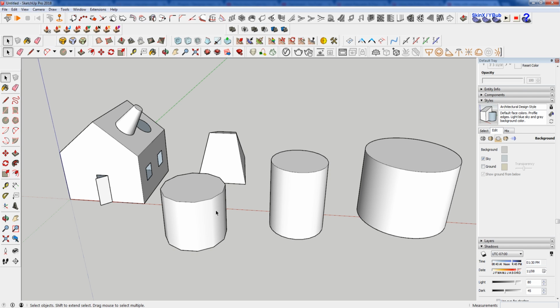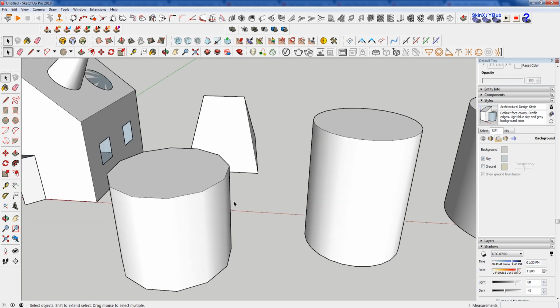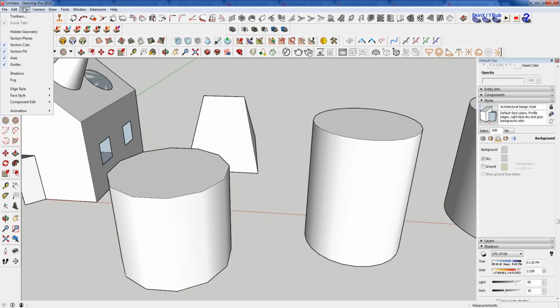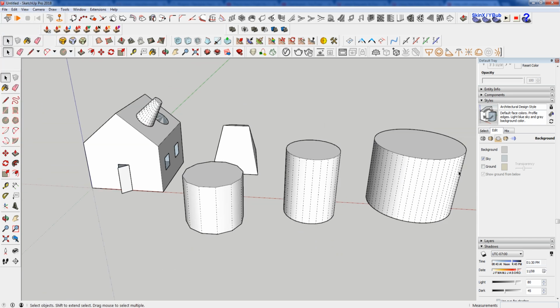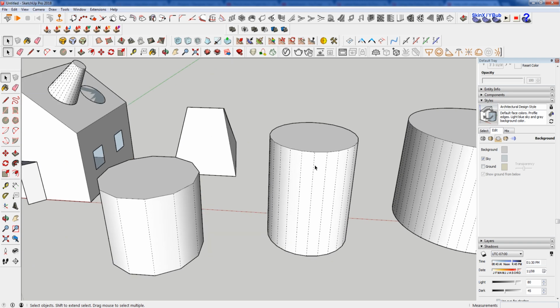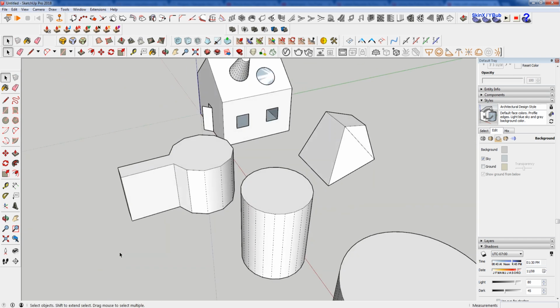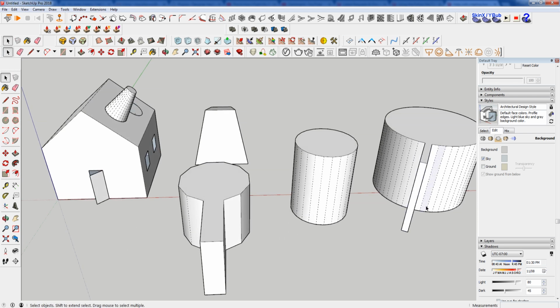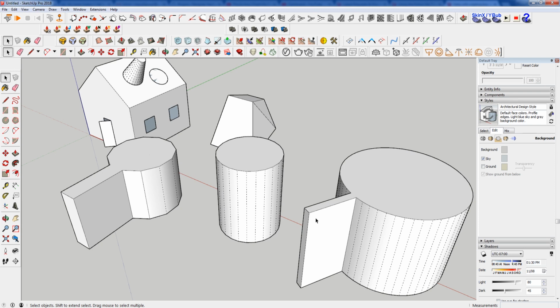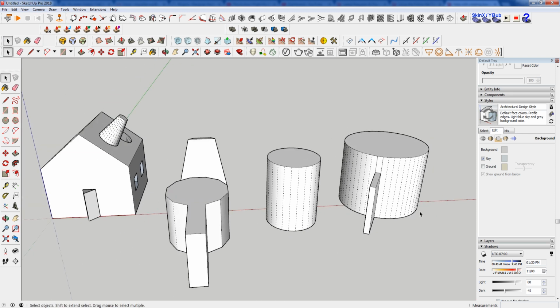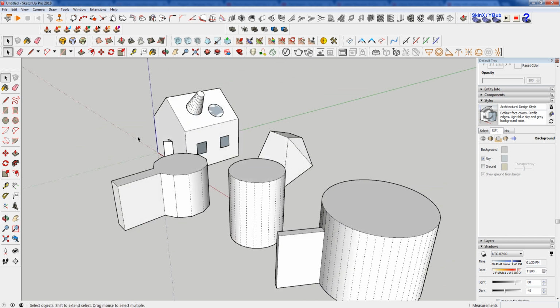So just something to think about as you go through, and it helps you understand the way SketchUp is working. Because if I turn on Hidden Geometry, you can see all those facets. It helps you construct things in a certain way. Knowing that these faces are flat, I can then come in here and extrude that piece on any of these because I have hidden geometry shown. I can show that, and maybe I just want to come back in and draw that line back in and move this down a little bit. So just understanding that that's the way SketchUp is working is important.